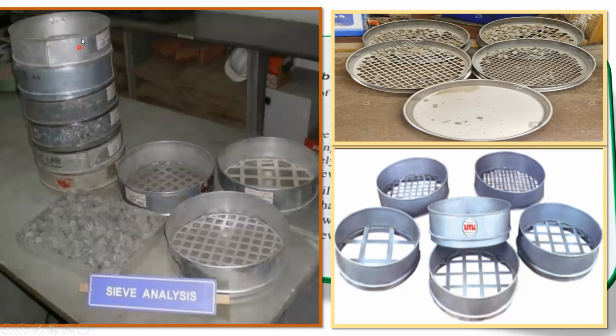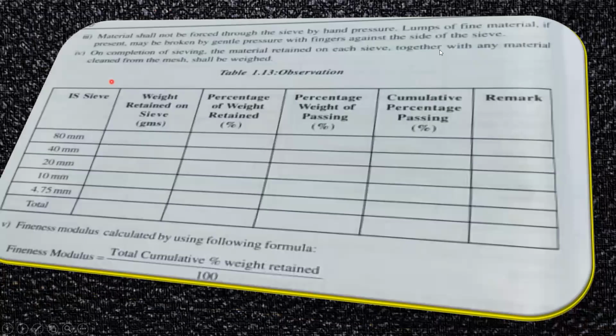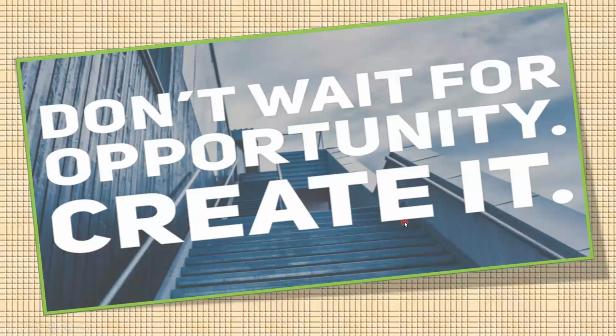The bigger one will be at the top, followed by the lower one, right? That's it. And again, the same table you have to make here. Again, the fineness modulus you are going to calculate as total cumulative divided by 100. Whatever answer you get, you are going to write it here as the fineness modulus of that, right? I hope the basic understanding is clear. We have covered the fineness modulus of the fine aggregate and also the coarse aggregate.